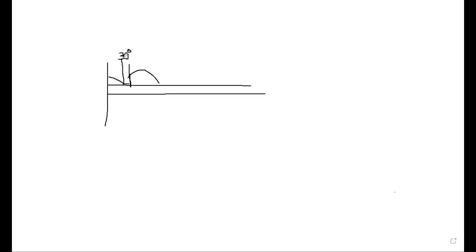Because when the firing angle alpha was 0 degree, then in this half-wave three-phase controlled rectifier it is starting its conduction from 30 degree.